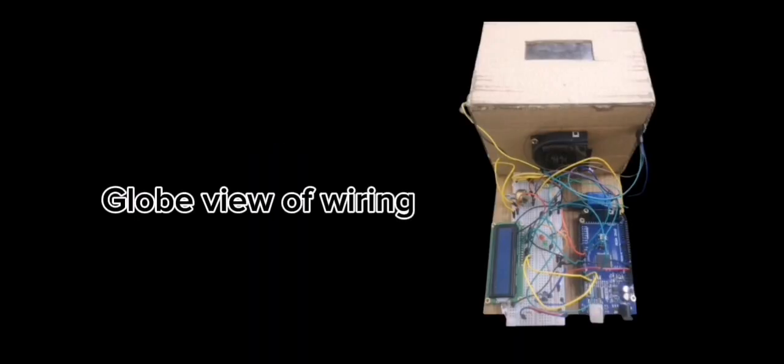After validating the system's behavior through simulation, we now move on to the real implementation using Arduino. In this section, we will explain the system wiring in detail. The wiring connects the sensors, actuators, and display element to the Arduino Mega to ensure temperature measurement, comparison with the set point, and control of the heater and fan. All components are mounted on a breadboard and connected to the Arduino using jumper wires.